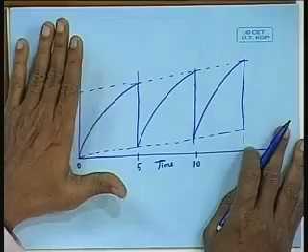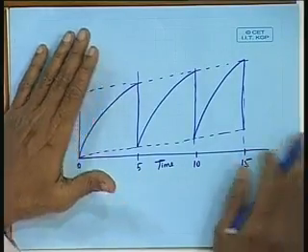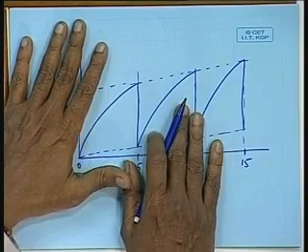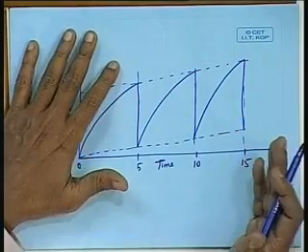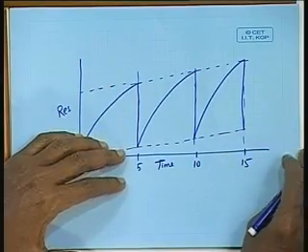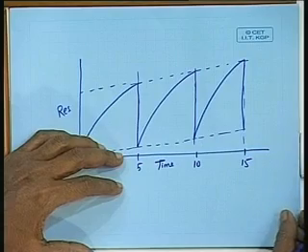Now, the resistance increase due to roughness can be calculated using this formulation if we know the roughness Ks of the ship at any time. But it is very difficult to estimate the resistance due to fouling because of the uncertainty in growth of fouling, as I have said. If we can estimate the resistance increase from the measured speed, we know at what point of time we require to maintain the hull. Maybe a scraping of the hull, removal of fouling even in afloat condition may be desirable.